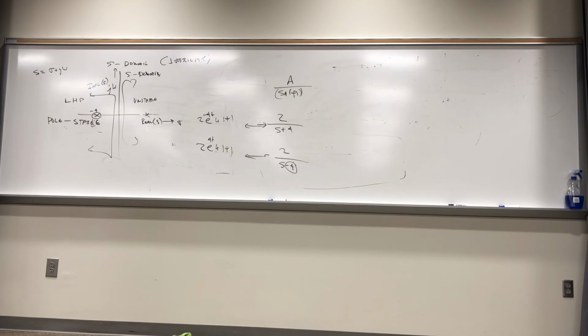So when you fed the output from your actual amplifier into this filter, you got something that would throw in power at all the different frequencies that would make the frequency response flat. Follow me on this, guys? So he basically allowed the filter to invert the bad performance of the speakers so you get flat output. He took cheap speakers, but he used an active crossover. It's called Bose 901. I remember these very well. And that sounded unreal. He used cheap speakers, but an active crossover to get unreal sound because he was in electrical engineering.